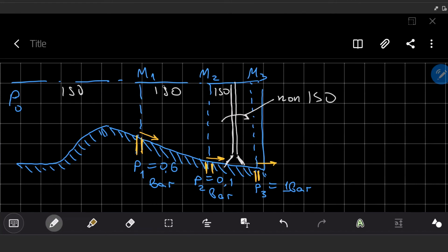If we see that we have isentropic flow in these first 3 regions, we understand that automatically P0, stagnation pressure, would be constant for all these flow regions. So for this region, and for this region, and for this region as well, it would be a constant value. Once we define P0, we can use it for any region.